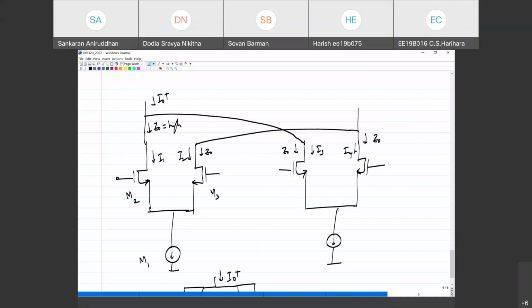Sir, in that passive mixer noise calculation, we have taken an approximation from 0 to FLO by 10. In that small frequency range, that noise would be common in both the outputs, right, sir? While switching from the hold to tracking mode and tracking to holding mode.